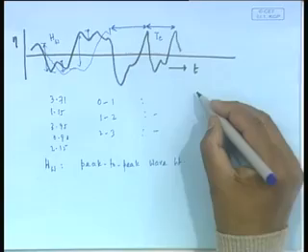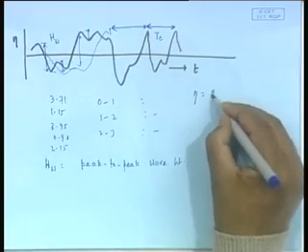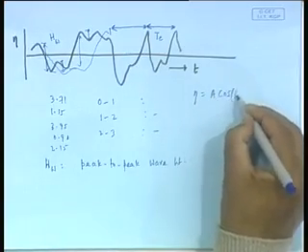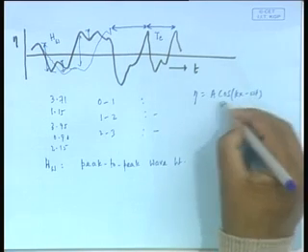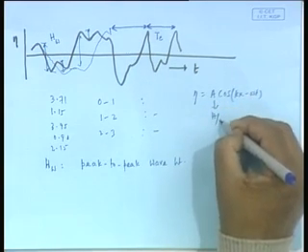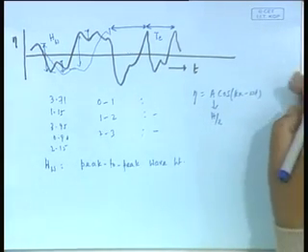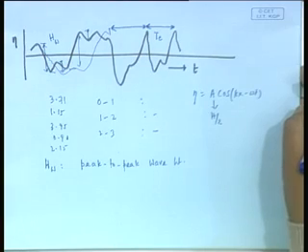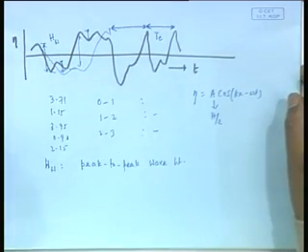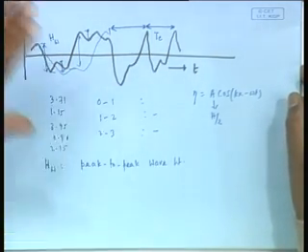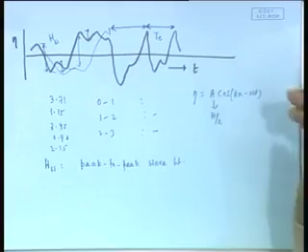When we talk of a regular wave, we have this A cos, and A is nothing but h by 2, but we normally use the term A, amplitude. What is amplitude? Measure of the crest or trough from the mean level, agreed.